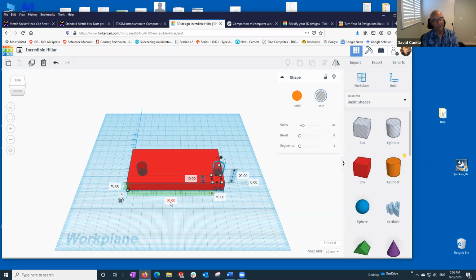Okay. So this is a little trick you need to know. What the ruler is measuring is the distance from the origin to the little left front corner, and I want to change that to measure the center of the cylinder. So I'm going to click on, see these three lines here? Use midpoint. There we go.